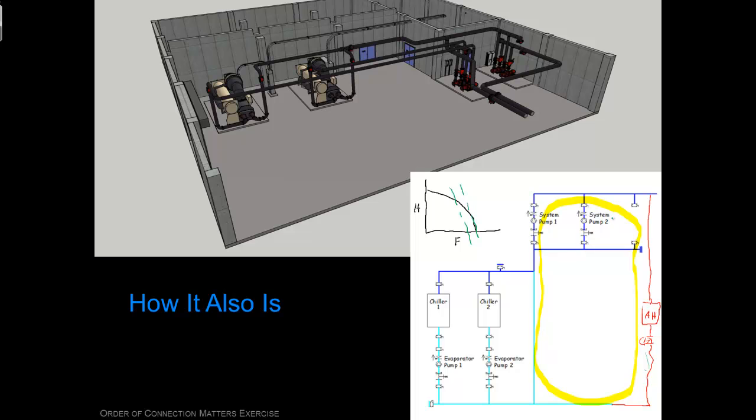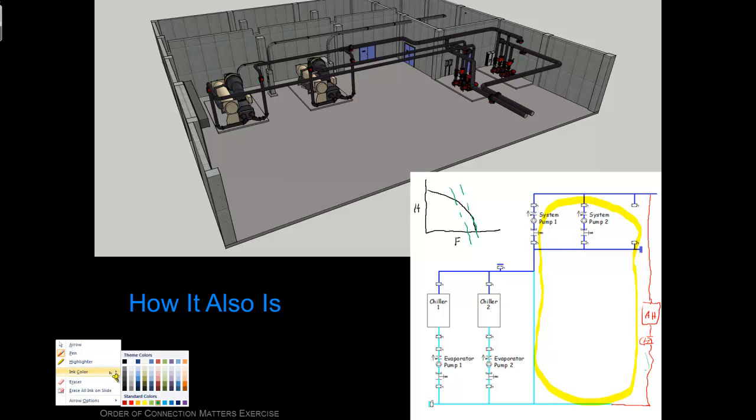Now, in newer systems, we usually have some sort of pressure sensing mechanism either at the pumps or out in the field if we're optimizing. As this valve throttles, the pressure tends to go up. The sensor sees that and says, oh, I can run the pump a little slower, and slows the pump down. So instead of being shoved up and down the pump's impeller curve, you end up moving the system around on the pump